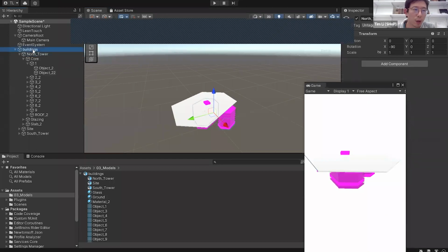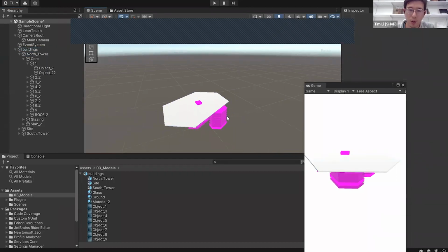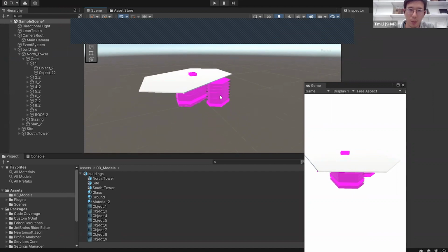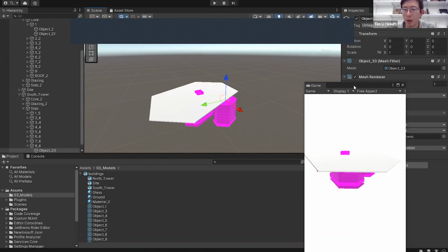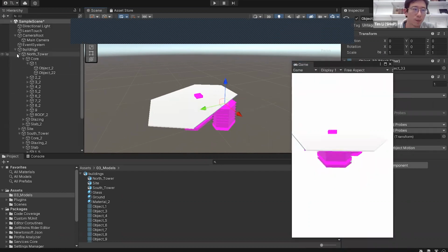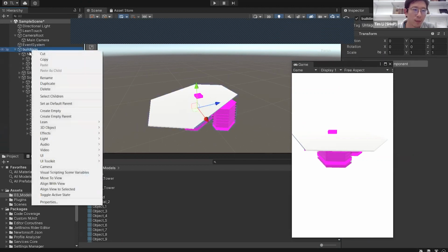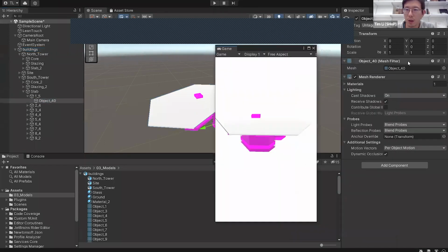So in order to break the link completely, you need to unpack completely. And you notice what just happened too. It turns pink, which means it doesn't have any materials applied to it. Previously they all showed up white because that's just the base material. The reason being, we've unpacked it at the base level and the geometries are still linked here.